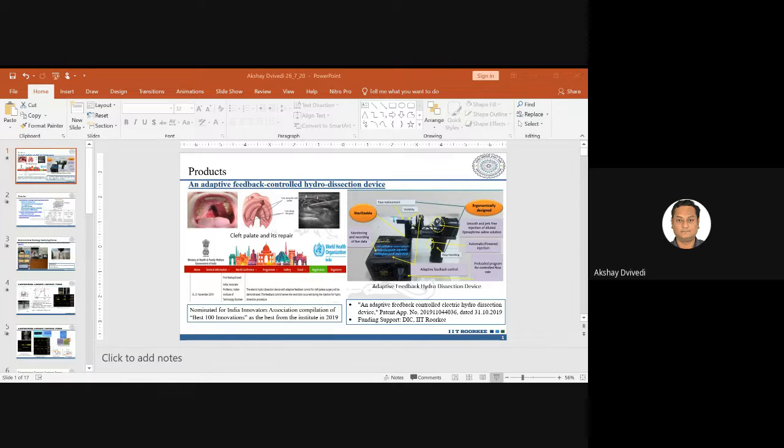What is the end result? The end result is, in earlier cases, people were facing difficulty going deeper than 300 micrometer depth. Some were having results of 400 micrometer, some were having a maximum of 500 micrometer. After that, this process was not serving the intended purpose. What you see here in the figure, when we go with this kind of approach, is a cross-sectional view of a machined hole wherein the depth is around 1350 micrometer. And this is created from this same tool.